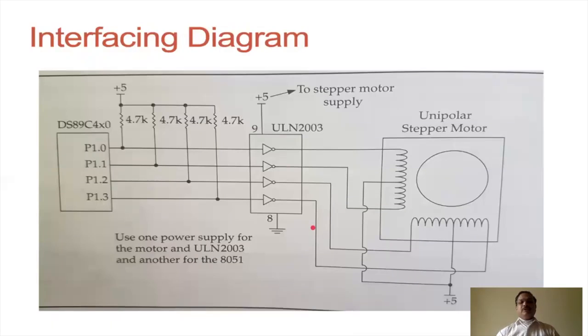Now here it shows the interfacing diagram. We can see the port 1 that is used as output port to output the step sequence, and here you can see using the driver ULN2003, it is interfaced with the stepper motor.